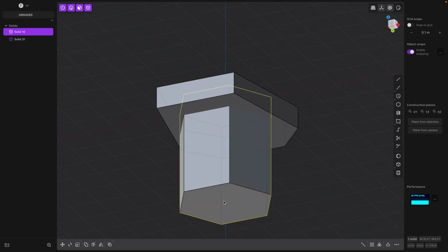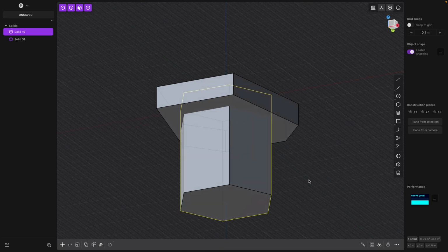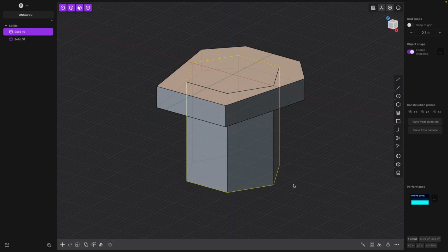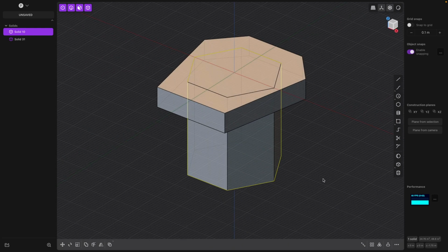In Plasticity here, if I wanted to change this peg, I would probably actually just delete it and create a new hexagon of the new diameter, and then try that out, rather than trying to adjust what was already here. So just, I think, keep that in mind.